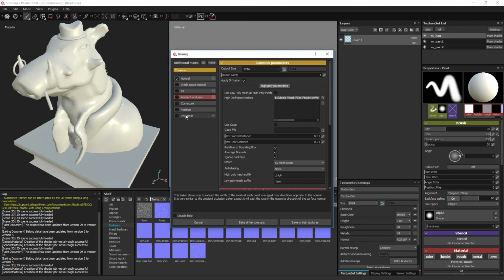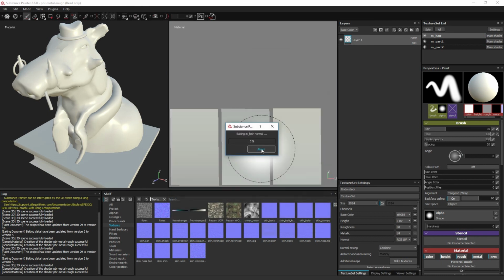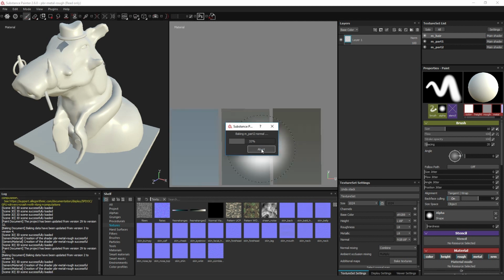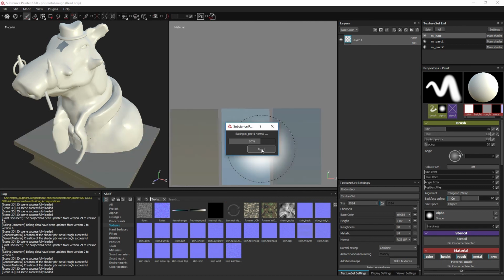Keeping the texture size at 1024 x 1024 and the anti-aliasing to none will result in a very jagged texture map, but the only thing you should care about now is that the projection rays do not render foreign objects into parts of the normal map where it doesn't belong. Once you got a successful bake, you can enable the other textures and increase the resolution and the anti-aliasing factor to get cleaner or clearer textures.